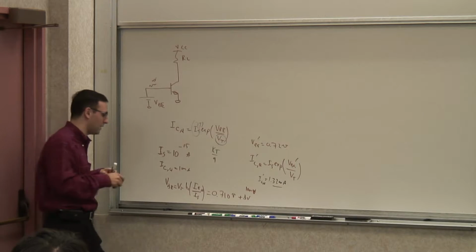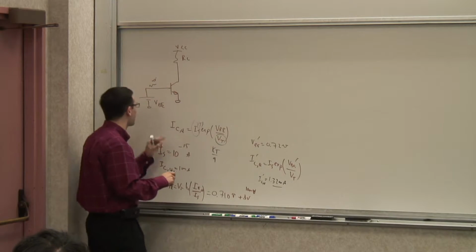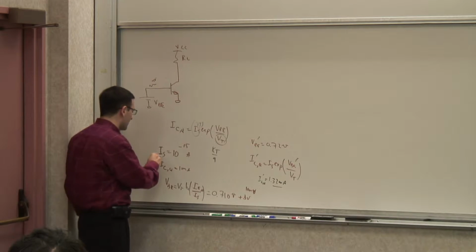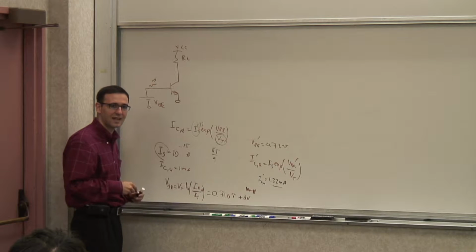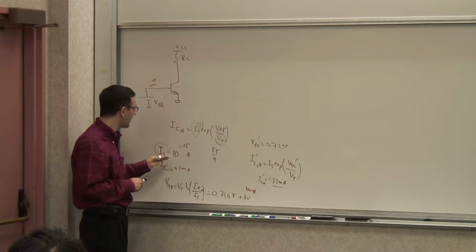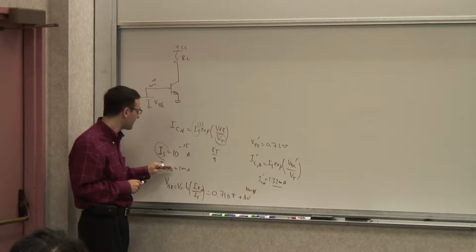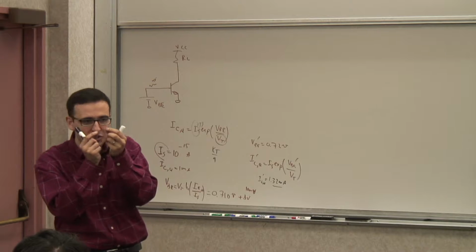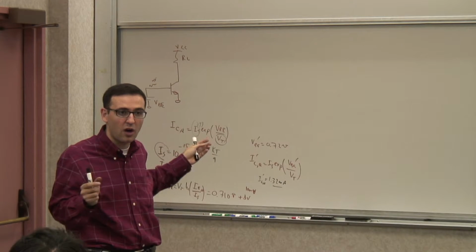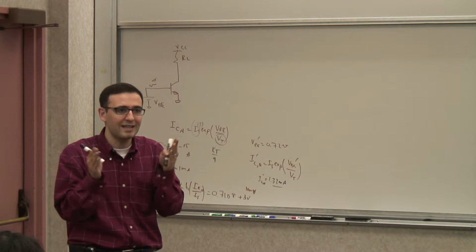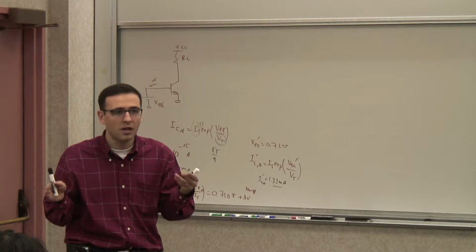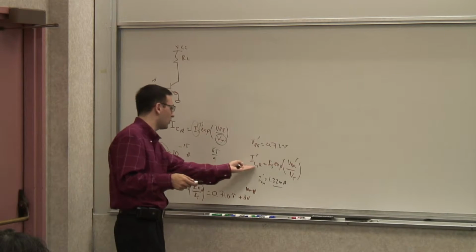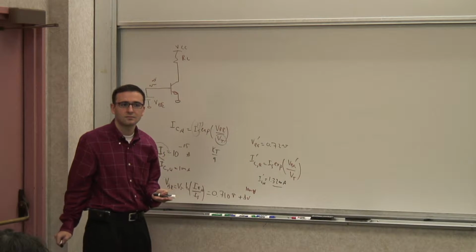The other thing that's kind of implicit: even if the temperature were kept constant, say I magically keep this voltage constant and magically keep the temperature constant, there is this IS, which I assume is constant, but it can vary from one transistor to the next one. This parameter is very sensitive to the dimensions of the transistors. So if the actual shape of the transistor is slightly different from one to the other, and we saw that you could not make two identical transistors, that would result in a variation in IS. And if IS is different, then the IC will be different, proportionately.